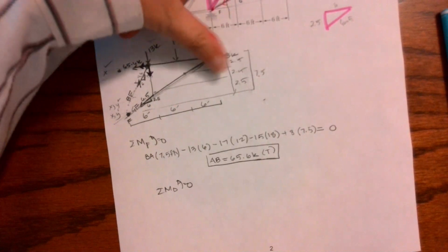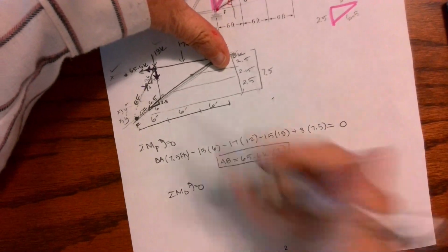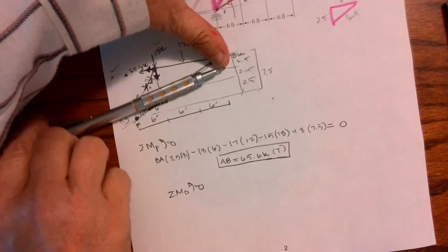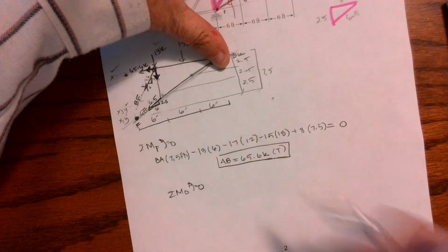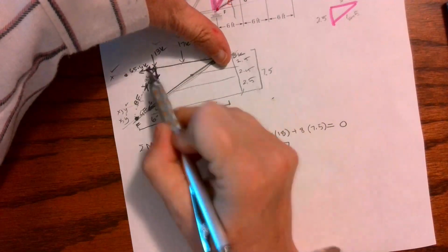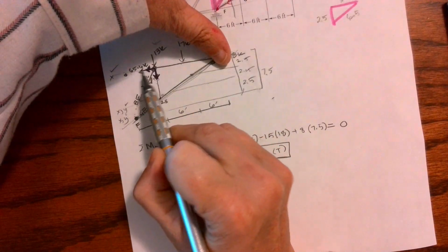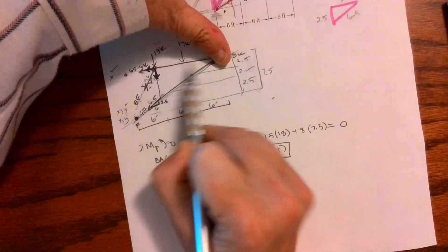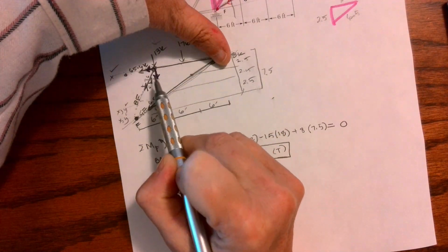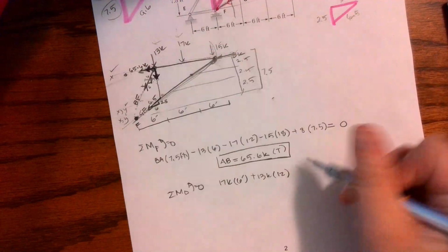So we're coming back here, my thumb, okay. When I look at my thumb, 8 and 15, translation, not rotation, they're right there. But I'm going to have 17, and if I attach my clock handle and push down, positive rotation, so I have 17 kips, and it is 6 feet over. And then I've got plus 13 kips, it is 12 feet over. I've got this 65.6 straight through, translation. I have the X component of BF straight through. So the Y component is that 7.5.